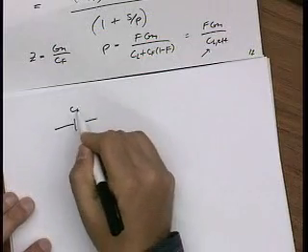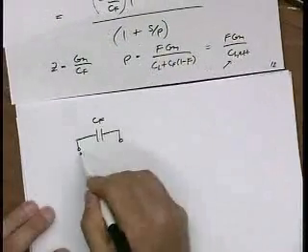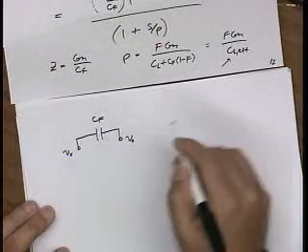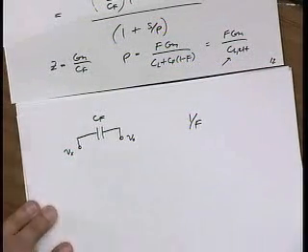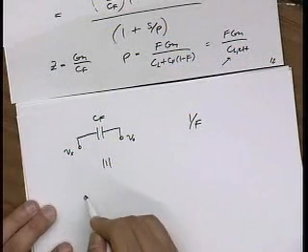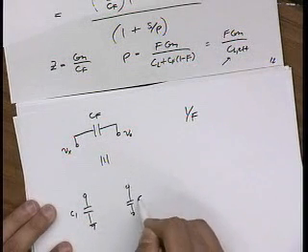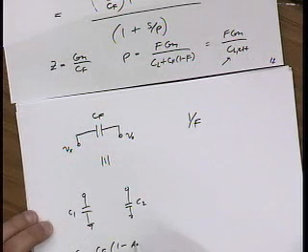I have a capacitor CF. What's the gain from the terminal Vx to Vout? Well, in a closed loop, it's just 1 over F, right? So then this is equivalent to a capacitance, let's say C1, and a capacitance C2. C1 is CF (1 minus AV), right?